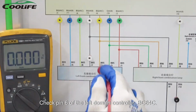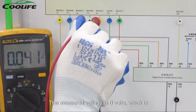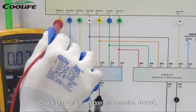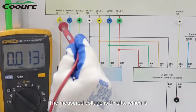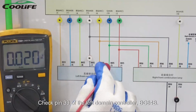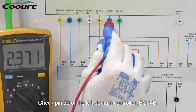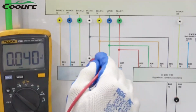Check pin 6 of the left domain controller, BG64C. The measured voltage is 0 volts, which is normal. Check pin 3 of the left domain controller, BG64C. The measured voltage is 0 volts, which is normal. Check pin 39 of the left domain controller, BG64B. The measured voltage is 2.4 volts, which is normal.